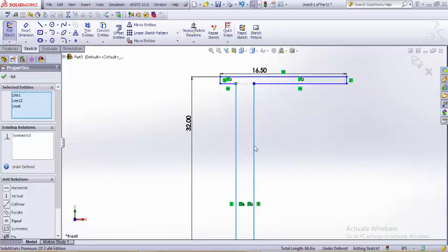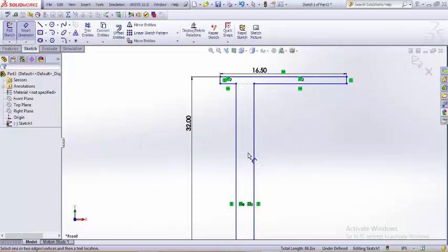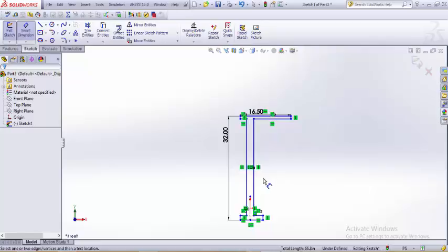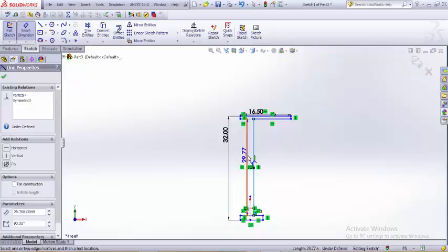Alright then, now for the thickness, the web, this connecting part is called the web, and this does not usually take any of the bending stresses, so it's pretty much thin compared to the other parts.